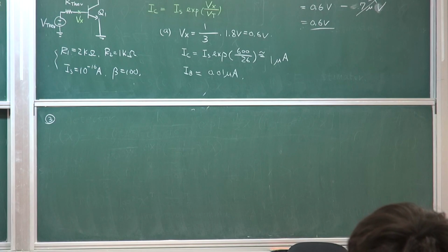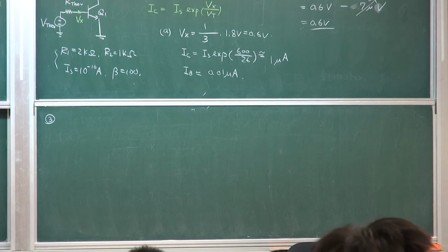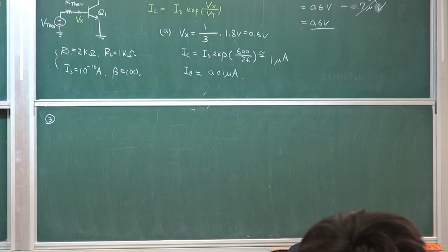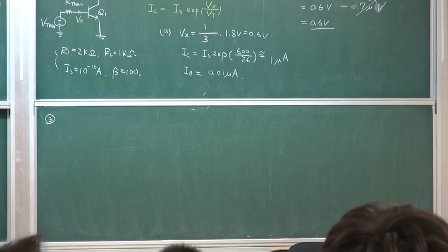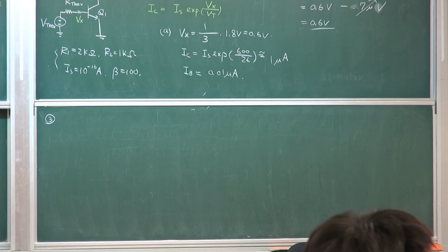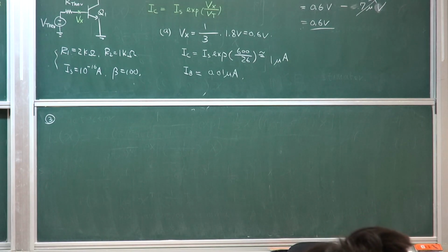So this 0.2 volt variation will come into your current, and your biasing current, which is supposed to be a DC component, varies throughout the supply cycle, for example. So this is not a very desirable parameter because it's very sensitive to Vx. If you have a small variation in Vx, it doesn't matter where it comes from, it's inside the exponential, therefore your IC control will be amplified.